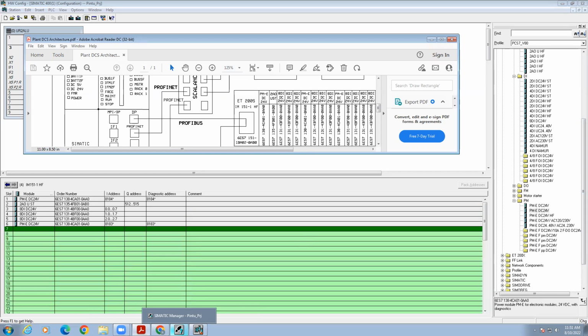It depends on your requirement. My requirement was a cheaper option, so that's why we purchased it. If you buy rack-wise slots, this is a rail interfacing module. We have a DIN rail, and on the DIN rail we keep these modules: power supply, 8 inputs, 8 inputs, power supply, 8 inputs, 8 inputs, that way. So we need to keep a separate SMPS.